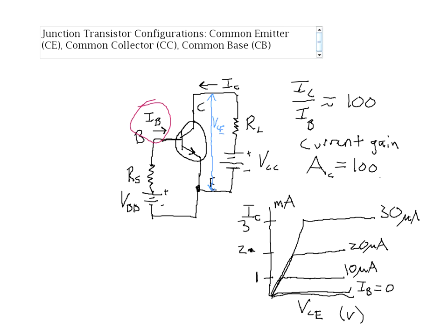And notice that as long as we're above about 1 volt or so, that actually does not depend on the value of VCE. That's important later in some applications.